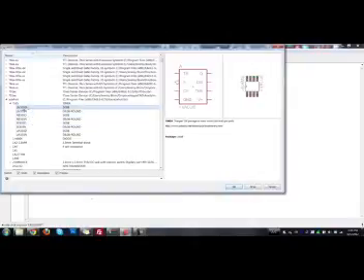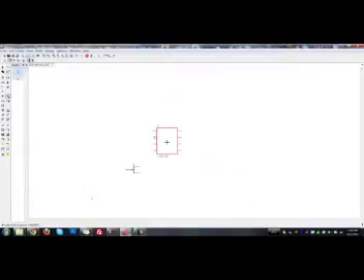But we'll be using the LM555D, and so we'll click that one. You can see it has a schematic version and the pad layout version that we'll be using later on when we do layout. Hit OK and drop that down. Okay, now we've got that too. The last few things that we're going to need are 2 capacitors, 4 resistors, and 2 LEDs. So again, I'll hit escape.